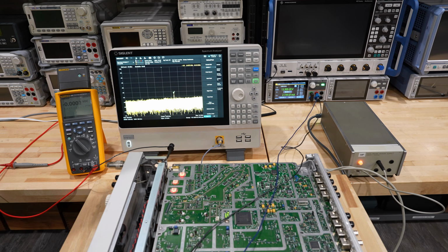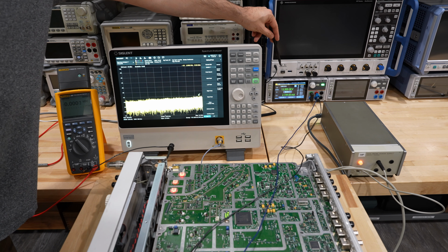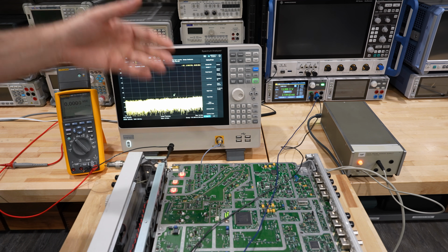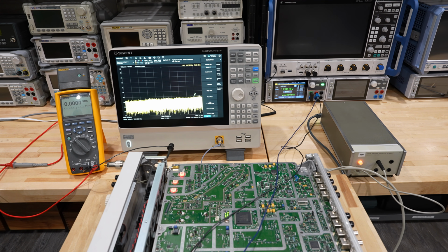You can see all the way in the back, I have the Rohde & Schwarz source measure unit there providing 14 volts right now, overriding that voltage. And you can see that it is drawing a couple of milliamps, of course, because the op amps inside of the control circuit are also trying to write into that voltage, but I'm coming in with a much lower impedance, so therefore I can override it. And the active probe is connected to our spectrum analyzer once again. Let's take a look at the VCO tuning frequency range.